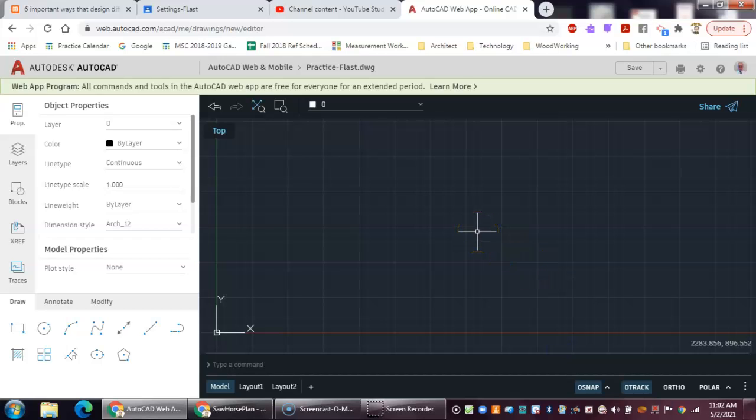All right, now we're just going to have fun doing a few things here as we make some lines and draw some basic shapes. So I'm going to start out by drawing a rectangle. And I want my insertion point on this to be at the X and Y coordinate of 3, 2. Now notice where it says rectangle, specify first corner of the rectangle.